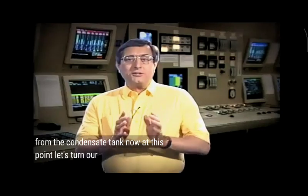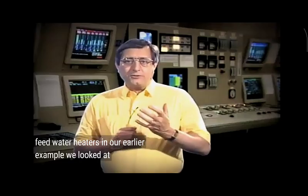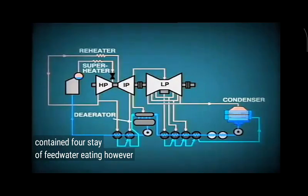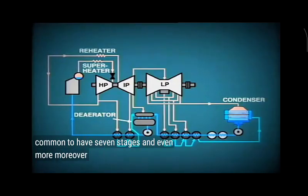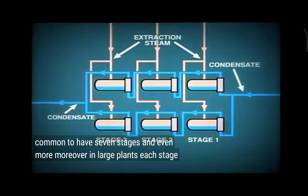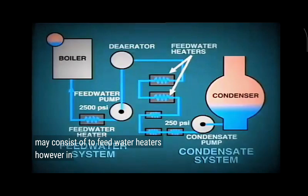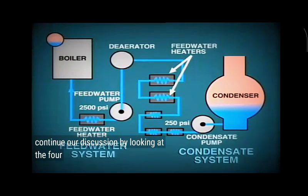Let's turn our attention to the feedwater heaters. In our earlier example, we looked at a system which contained 4 stages of feedwater heating. However, it is quite common to have 7 stages and even more. Moreover, in large plants, each stage may consist of 2 feedwater heaters. However, in all of this, the principle of operation is the same. So we will continue our discussion by looking at the 4 stages of extraction.